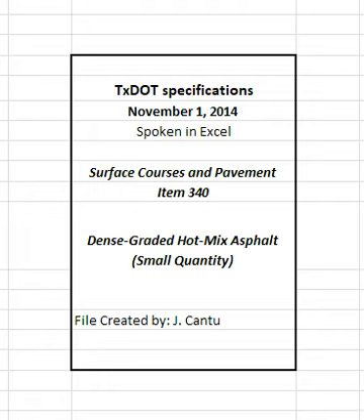The engineer may perform tests on independent or split samples to verify contractor test results. Stockpile aggregates for each source and type separately. Determine aggregate gradations for mixture design and production testing based on the washed sieve analysis given in Tex 200F, Part 2. 2.1.1 Coarse aggregate. Coarse aggregate stockpiles must have no more than 20% material passing the number 8 sieve.